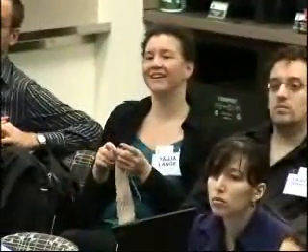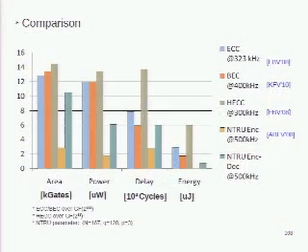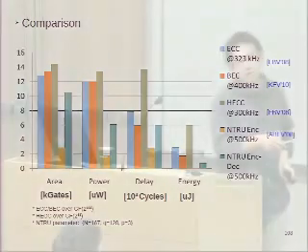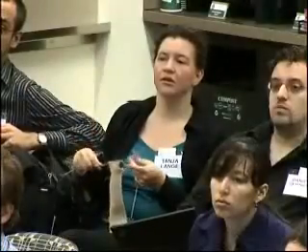What were your design choices for the chip that you now have? I mean, you presented different curves. So this chip, we actually used the 163-bit elliptic curve with the Montgomery powering ladder. So the one from the standards? Yes, it's a Koblitz curve.